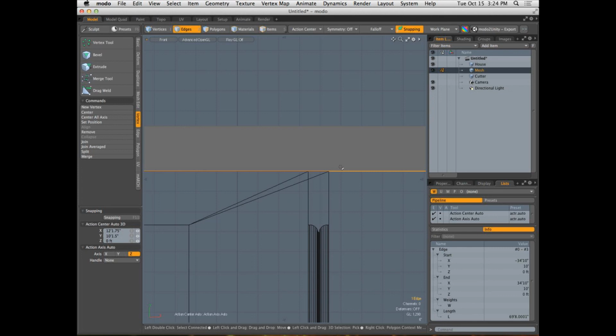But they're not very thick. If you really think about how it's constructed, there's plywood as the underlayment for your roof, and then there's usually some sort of tar paper or vapor barrier on top of the plywood to keep the water out, and then you have the actual shingles that go on top. So the roof isn't really that thick. It's not as structural as one would believe. So maybe it's only 3 or 4 inches.